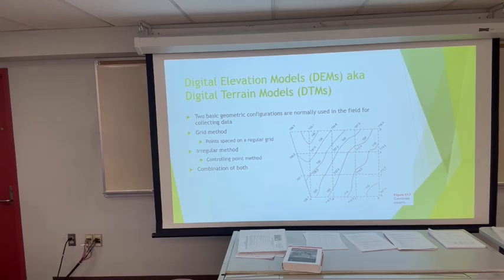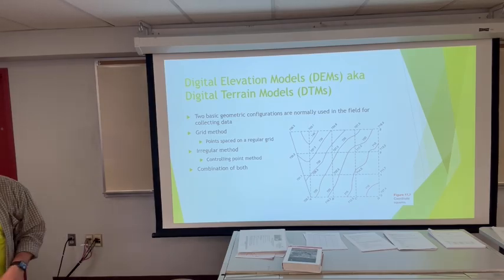Any questions on that? When I was out in the field, what I used to like to do, especially with a brand new co-op student, if we were topoing a smaller area, I'd break off a small area for them to do on their own and tell them, look for your break lines, get your break lines first, and then fill in the blanks where you think you need to get some extra ground shots so we have enough coverage. I would explain it a little bit more in detail, but that was more or less the watered down thing: when you're starting off, focus on your break lines and then fill in the blanks.